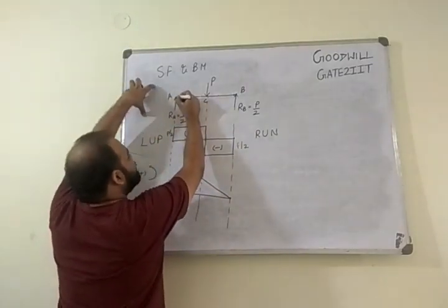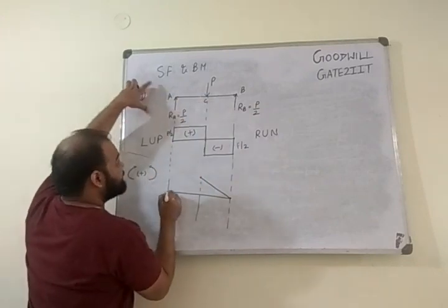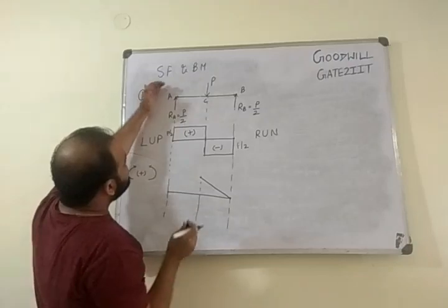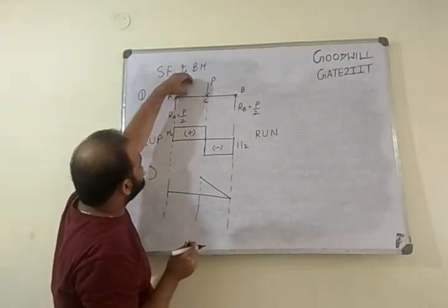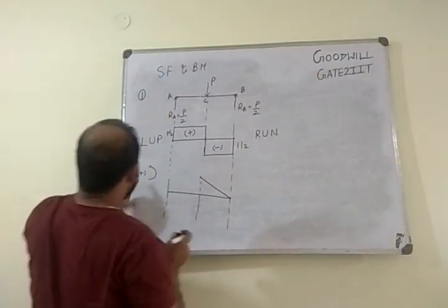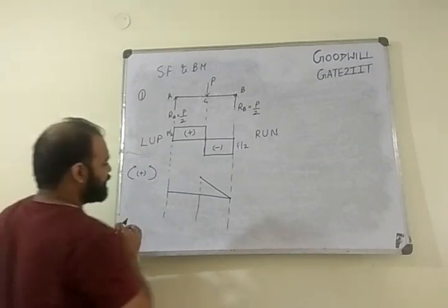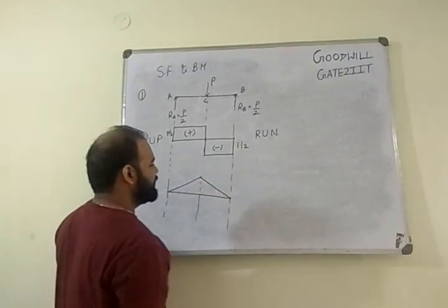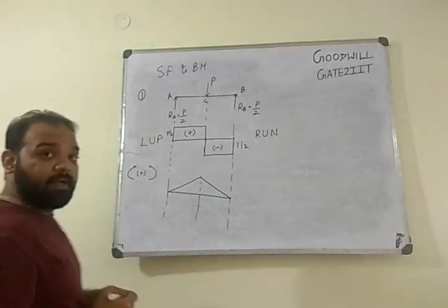Now same thing, what is the moment here? See what loads you have on the left hand side, no loads, right? So I'll start with 0. If you move forward, your moment is continuously increasing, and this is the moment it is creating, force into perpendicular distance at any point you can observe. And what is this moment? Positive for us when you move from the left hand side, start and you reach here.